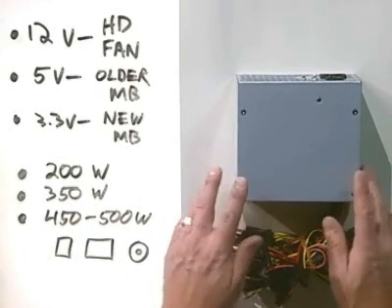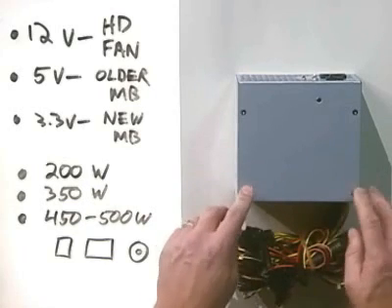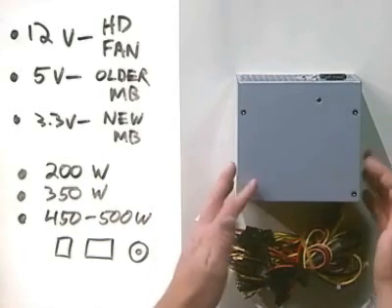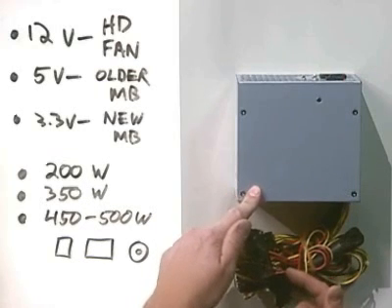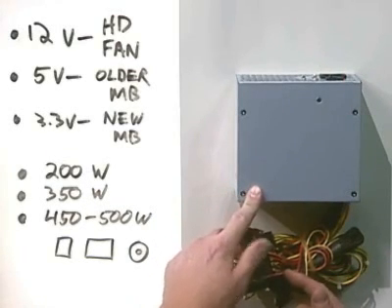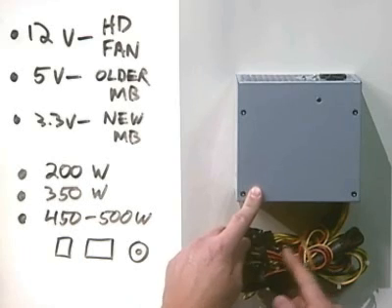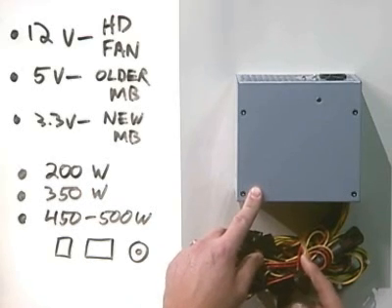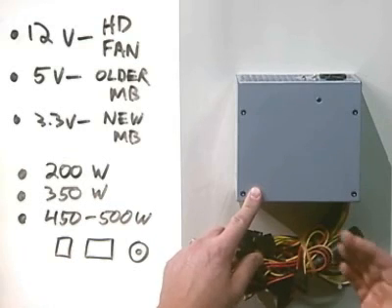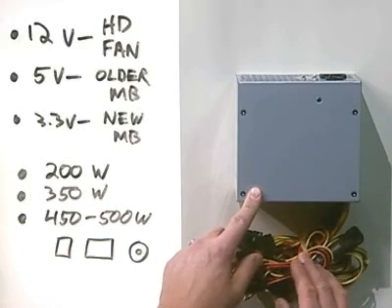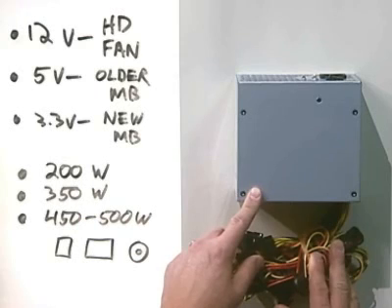And this is important because this power supply actually has a second job. Its first job, obviously, is to take 110, 120 volt AC current and convert it to DC current. But its other job is to ensure that there's enough power available to run the system. If there's not enough power available coming through the DC side, then the system will shut down.